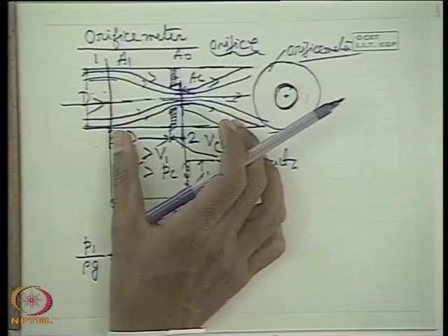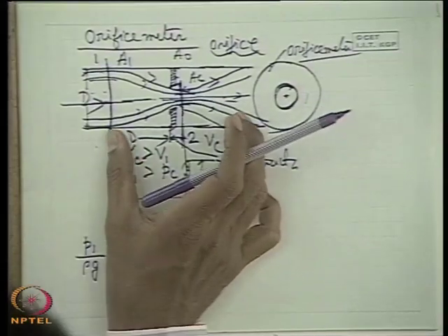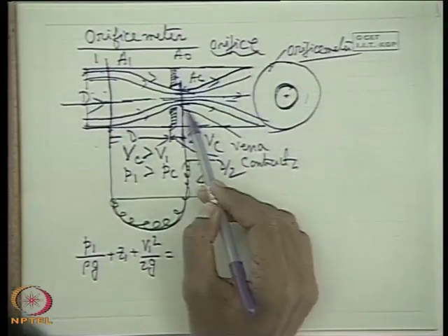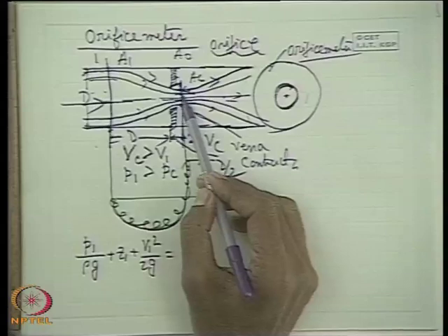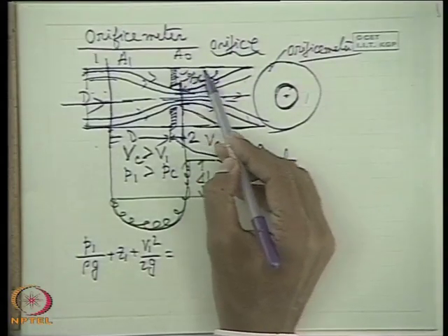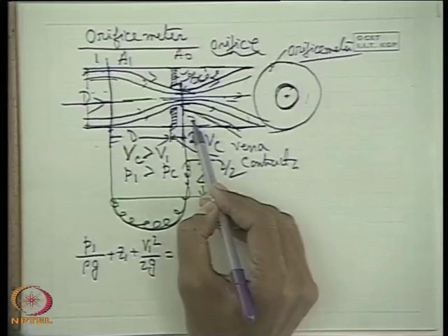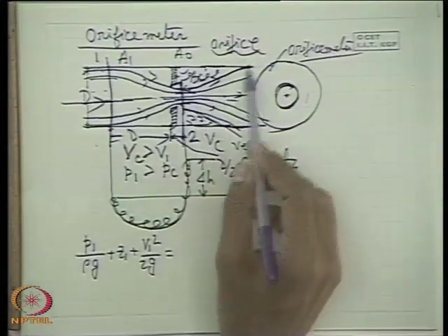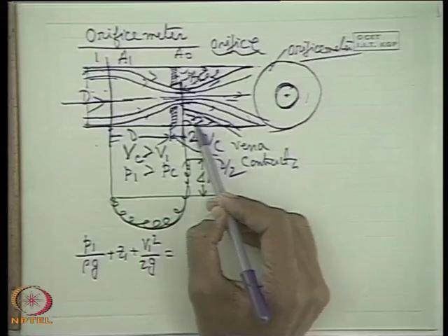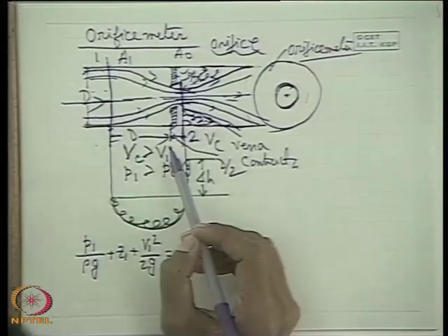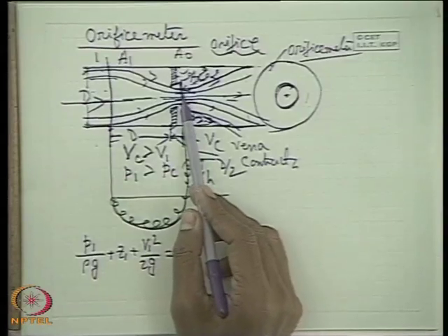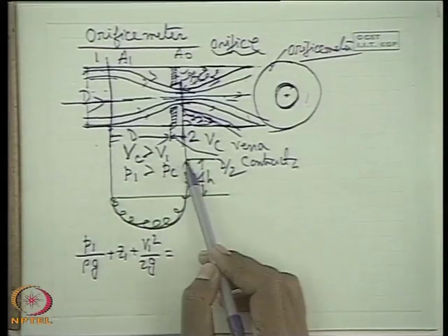In that case, a high value of delta P is very difficult to be registered because the fluid flow area is again expanding. So therefore the pressure is again increasing. You understand? So this part is the eddy portion. As you know, when the expansion is taking place, the fluid is expanding, that is diverging, streamlines are diverging, there are flow reversal zones. So therefore you now recognize that if we can attach the manometer at the vena contracta section, we can get the maximum pressure drop.